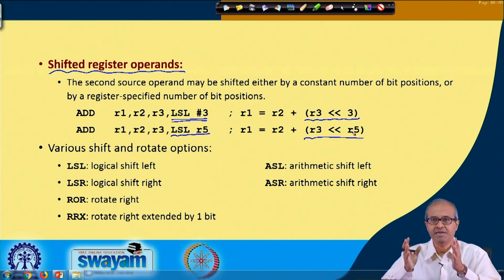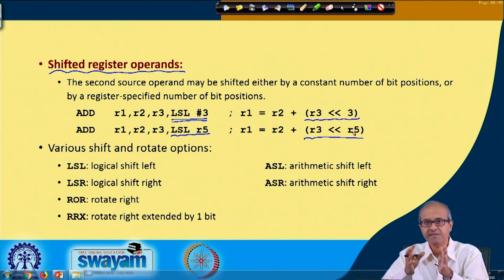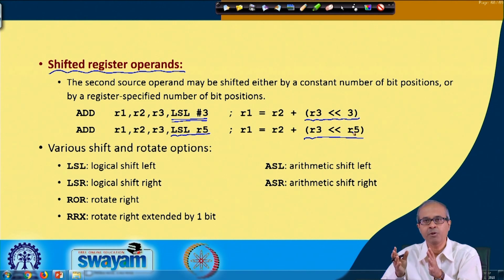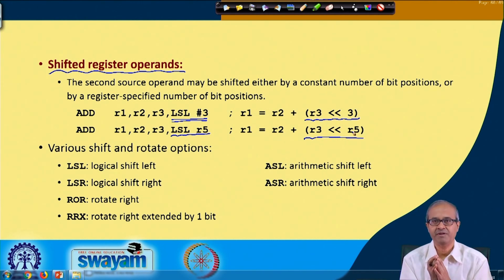Now, you see here we have a facility of specifying the second operand in some flexible way, either in the normal form or in some shifted form. That is why this reverse subtract operation you recall, there I can subtract a register from the shifted value of another register. That is why this reverse subtract facility is also there.